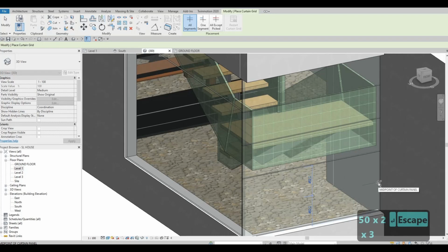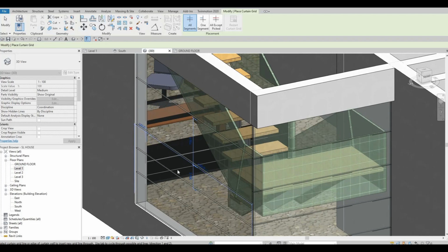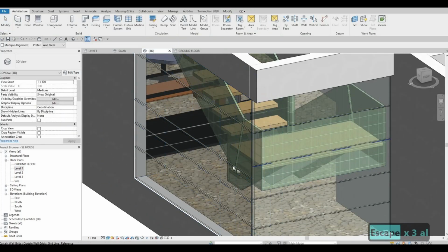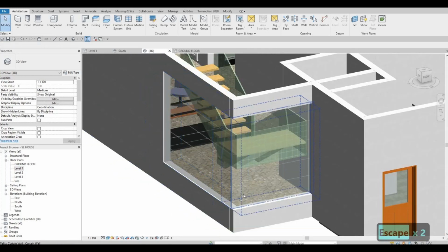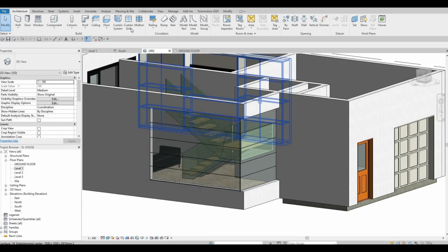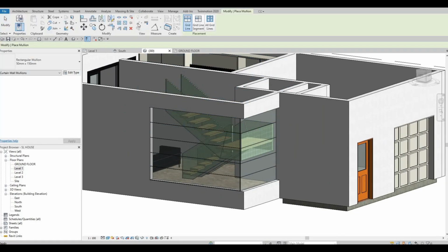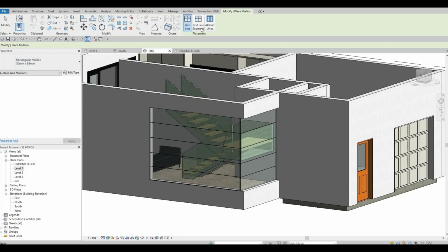and then just do this once you're there, so that everything is aligned. AL, select it there, and then you could just add it without aligning first, and then it will be like that. So now next thing is clicking on mullion. So here in mullion, what we can do is we could use 50 by 65 first.